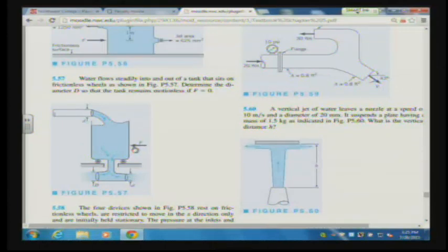And what that means is we would have to have some reactive force here unless the momentum here is essentially equal to the momentum here. But in this case, we have the possibility of water coming out this way. So we could have a momentum where the water coming out this way would push it in the opposite direction. So what we're looking at is what diameter do we need here if these two diameters are equal and the force is equal to 0.